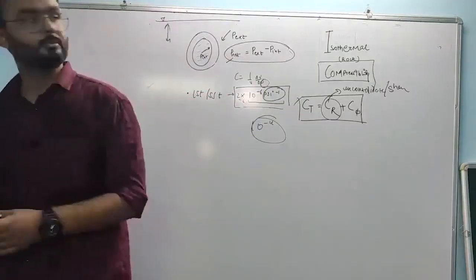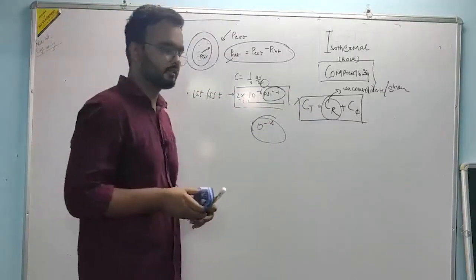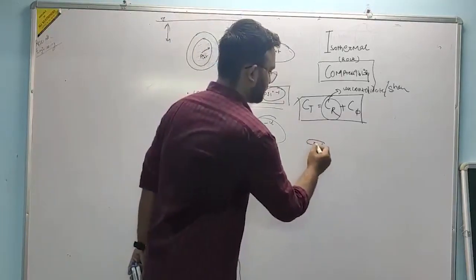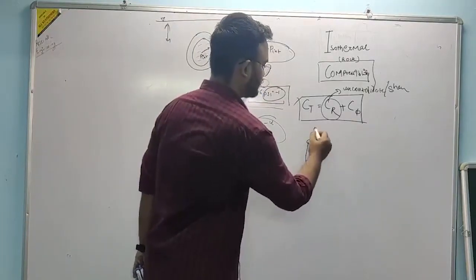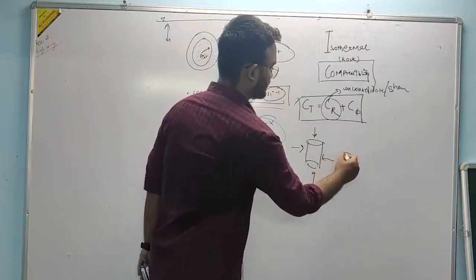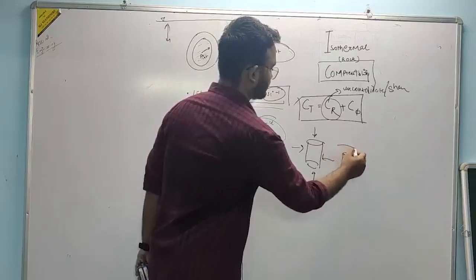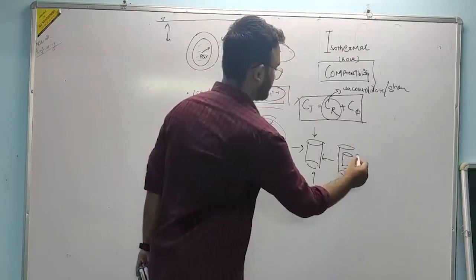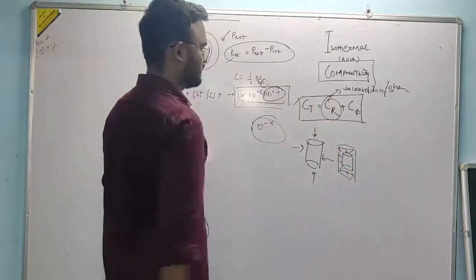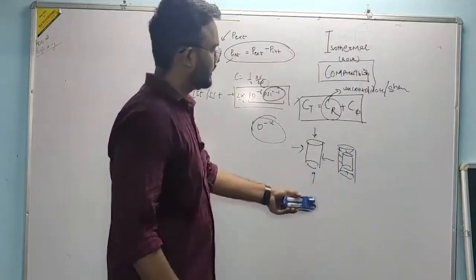How do you measure compressibility? There are triaxial cells in the laboratory. They have a rock sample and apply stress from every direction, trying to compress the rock as compared to its initial position. Then they measure the compressibility just the way I told you. Why triaxial?